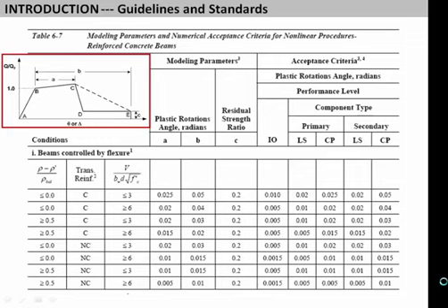But to me, the big improvement that came with FEMA 273 and ASCE 41 now is that it provides tables like these with modeling criteria for different kinds of structural components, in this case relating the deformation capacities and so forth, for reinforced concrete with tie spacing. And this is, I think, as a practitioner, what really lets you do nonlinear analysis and doesn't make it a research project each time to come up with your nonlinear analysis model. So I think we're building on ASCE 41.